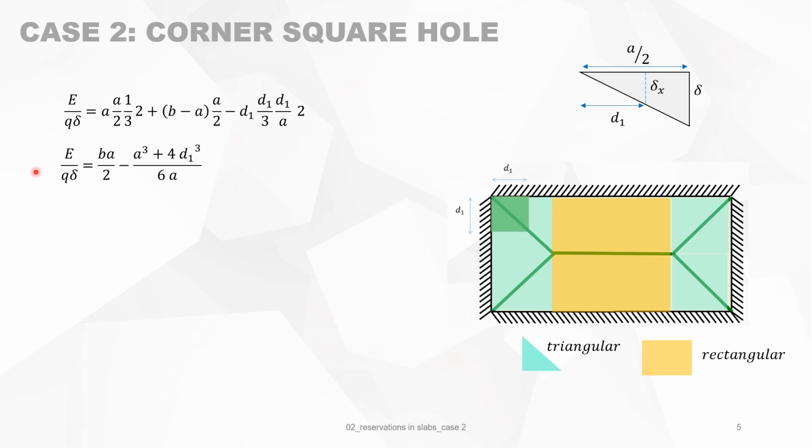So now we have the virtual work done by the external forces. We now look at the internal bending moments and their virtual work done. And there it's quite simple. We do the same thing. We take the work done for the whole slab without a hole, and we subtract the yield line here, which is connected to the rotation axis of there and the rotation axis of there.